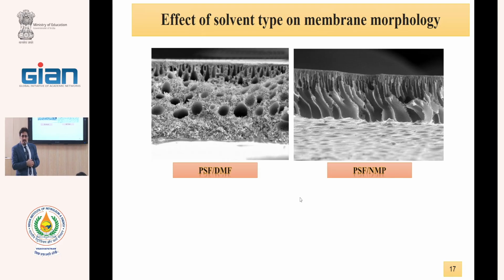Is it possible, in the case of the Dr. Blade coating method that we are doing, to go on adding different layers? Two layers, yes. We have devices that coat two layers continuously. Between the first Dr. Blade and the second Dr. Blade, we have a 5-6 centimeter distance. First one layer is coated and next the second layer. We call these dual layer membranes.